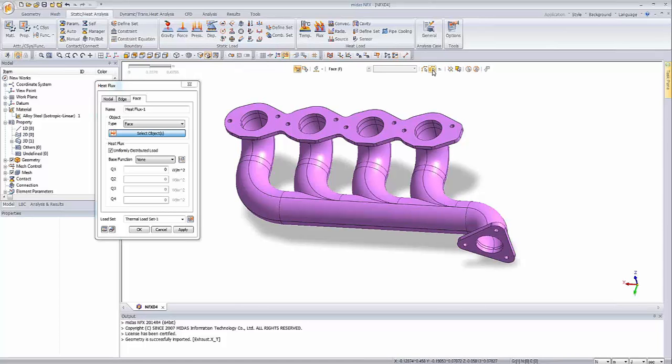So there is one option which is called select neighboring edges or surfaces with feature angle. We're supposed to start from this option and set up the feature angle. We can set 20 degrees, for example, or let's say 10. But I think 20 is quite a good option, and you're supposed to exercise this option by yourself. And now I will show you how to select all of those faces.